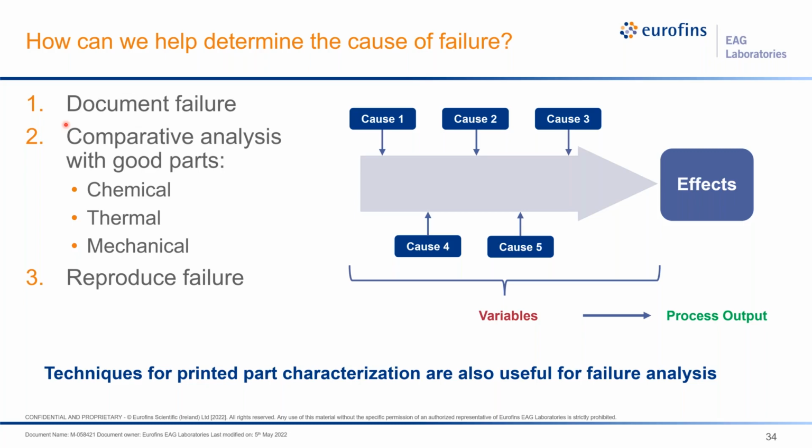And then we want to compare a good and a bad part. And we want to do a variety of tests, a lot of the material characterization tests that we talked about today, as well as functional tests, like how is this part used? Is it a mechanical part? Okay, we can do some mechanical testing, but we want to compare a good and a bad. Where is there a difference? What can we see as something that stands out? And so, sometimes we do FTIR, we don't see a difference, but we do thermal analysis and we do see a difference, and that might lead us in a certain direction.